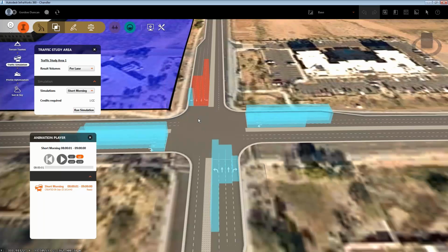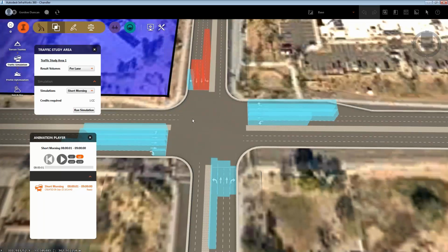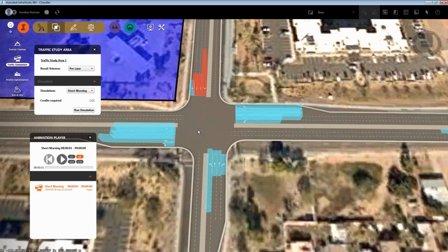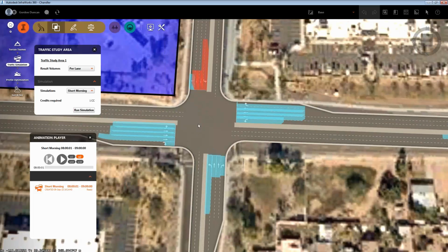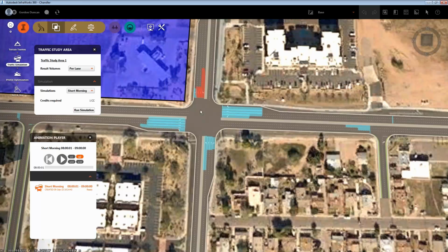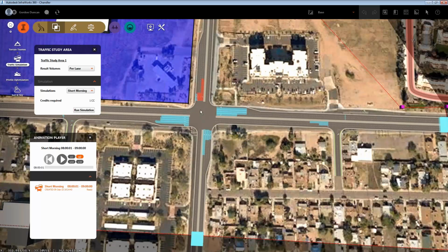And remember that this is a signalized intersection, so it's counting the time that they would just be stopped at the red lights anyway, waiting for their turn, so that's actually not too bad. The colouring is based on the Highway Capacity Manual levels of service, so anything level of service E and F is coloured red, and everything else is coloured blue. Okay, so that's showing you, given the traffic demand that we've taken from the DOT site and an estimate of what the traffic signals are at that location, what the traffic queues would be like.